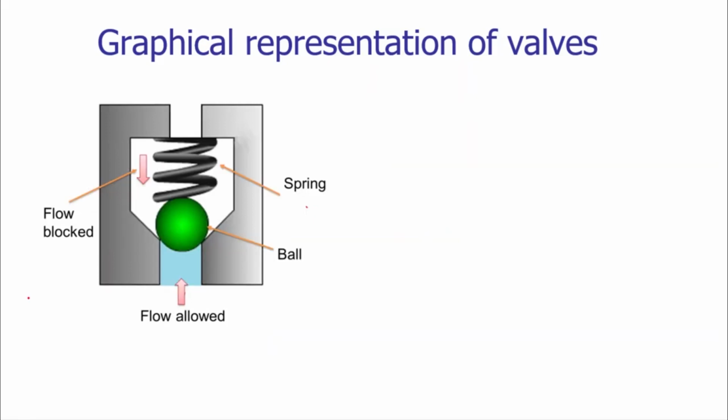Let us draw the graphical representation of the check valve, a very useful element of a hydraulic power pack. We have seen the working of the check valve in our previous lecture itself. The check valve is having a ball and a spring arrangement, and it is not allowing the fluid in one of the directions.